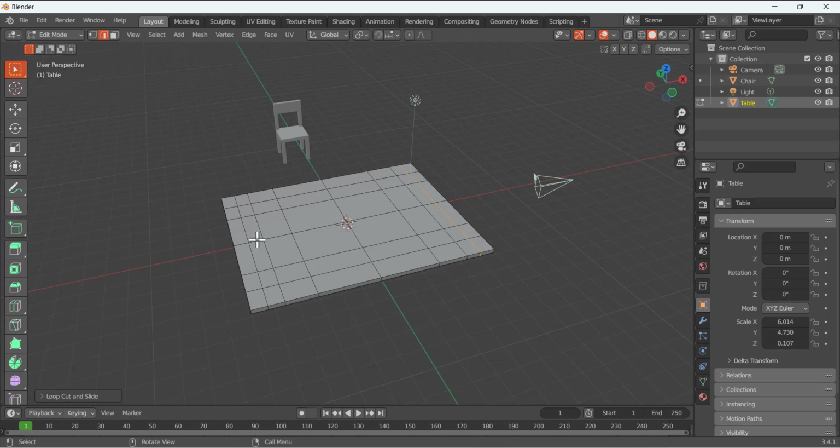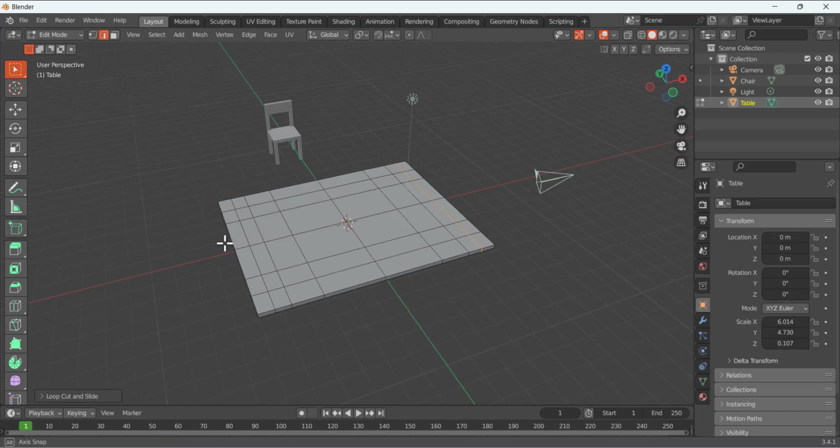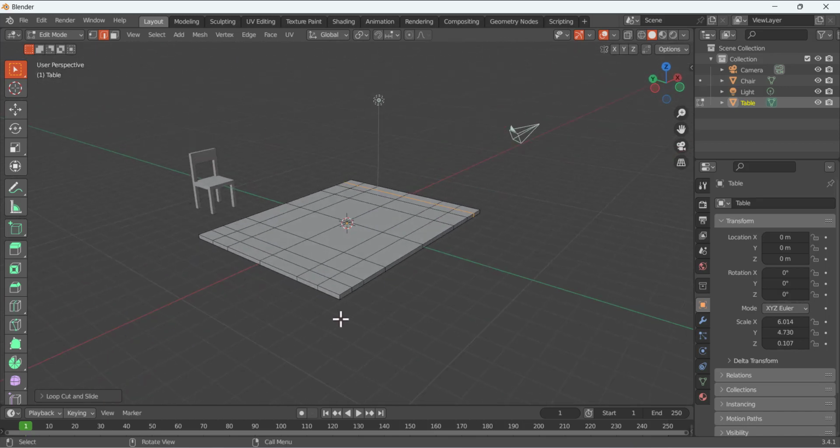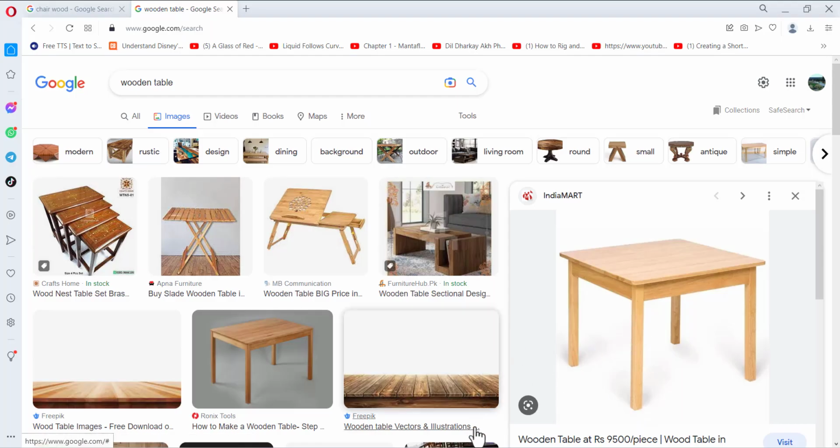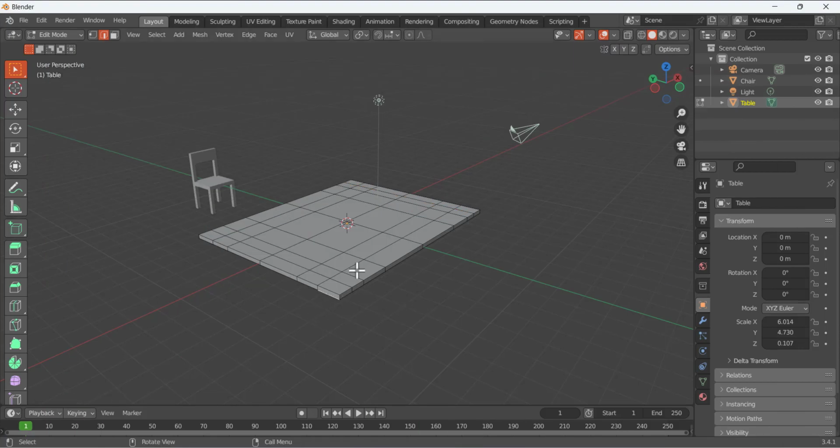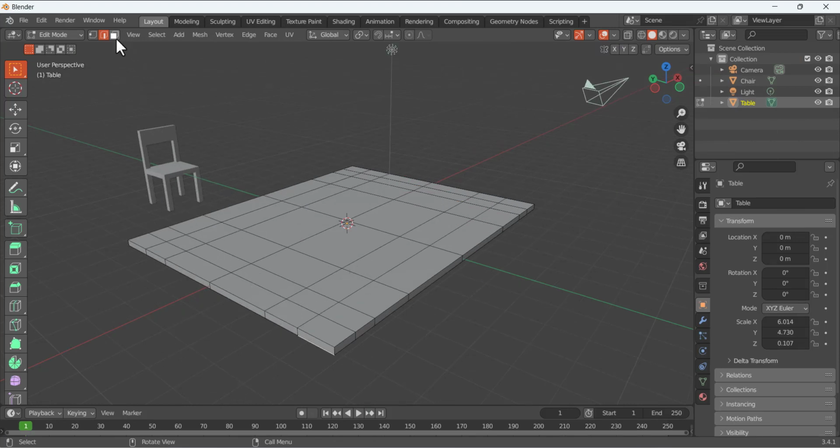You can see this on this origin. We have this equal loop cut in this way and equal loop cut in this way. We make these loop cuts to add the extra geometry so we can extrude these legs. Now I am going to make sure your selection is in the face mode.